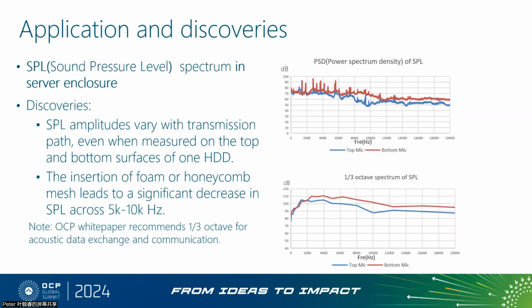Through the insertion loss curve, we found the sound dampening capability of porous foam ranges over a broad spectrum and dominates in the high frequency range of 7K to 9K Hz. When we change the thickness, material, or area of the foam sheet, the IL peak amplitude changes as well, but the dominant frequencies don't change.